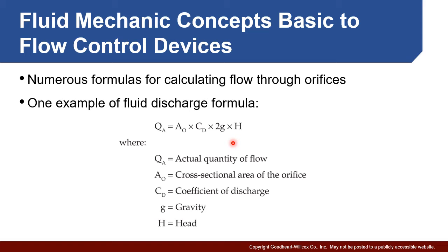And one thing to keep in mind is that even though you may calculate a flow rate, you really need to check that and make adjustments on it. And in fact, over time, you have to check all flow control valves and make sure they're still operating over time. There can be wear, different types of friction, and eventual changes in viscosity, all of which can affect the flow rate. So this is something you need to monitor because it isn't something you can just set and leave. It will change potentially over time to a certain degree.